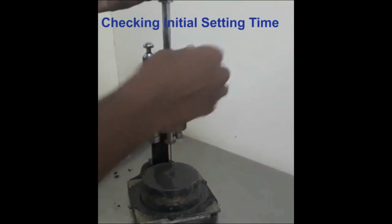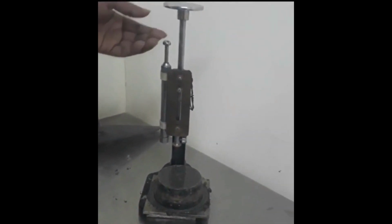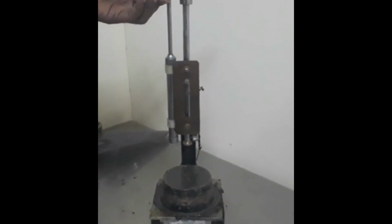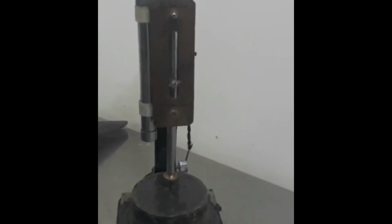The period elapsing between the time when the water is added to the cement and the time at which the needle penetrates the test block to a depth equal to 33 to 35 mm from the top is taken as the initial setting time. So the time after adding water till the time it reaches the 33 to 35 mm penetration is the initial setting time.